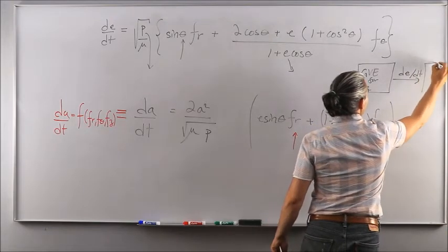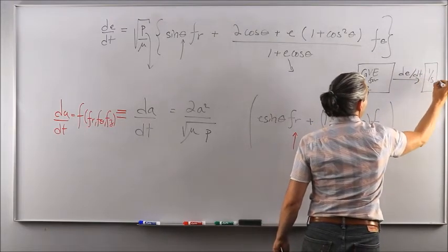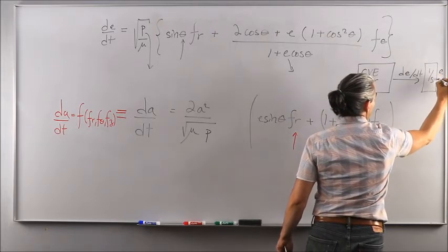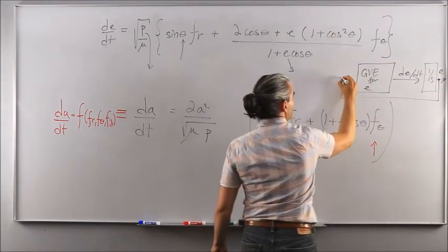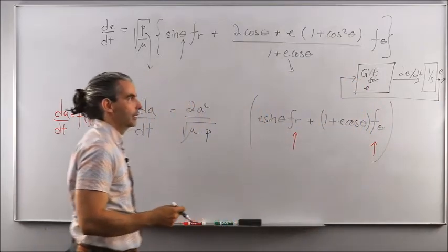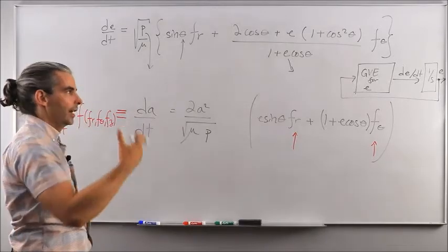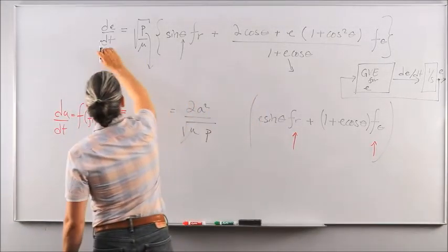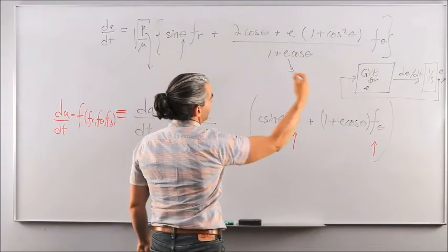And then what you would do is integrate that to get the actual eccentricity and feed the result back into the Gauss variational equation to calculate the new rate of change. Integrate that, get the new eccentricity, feed it back, calculate the new rate of change, integrate, new eccentricity, and so on and so on.